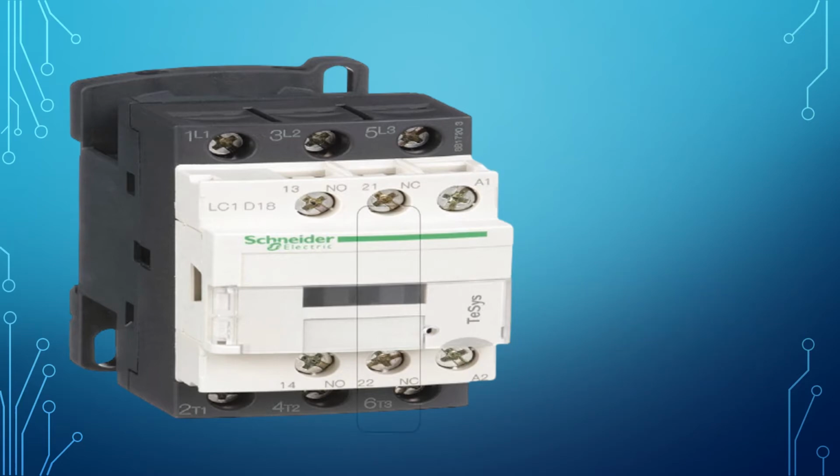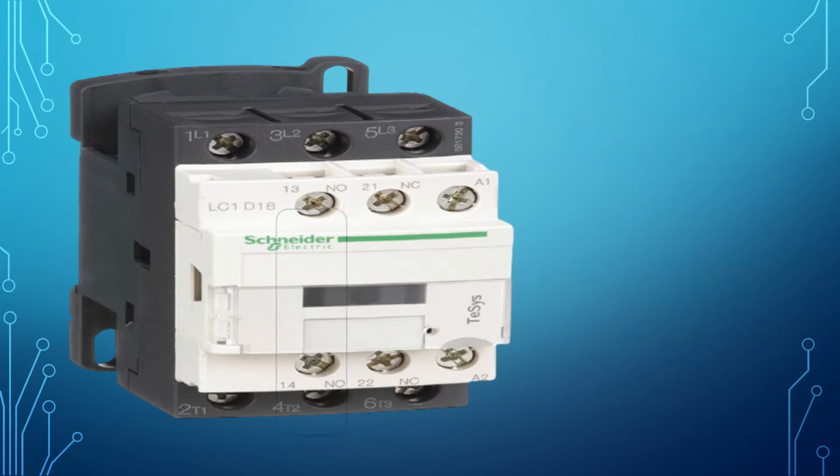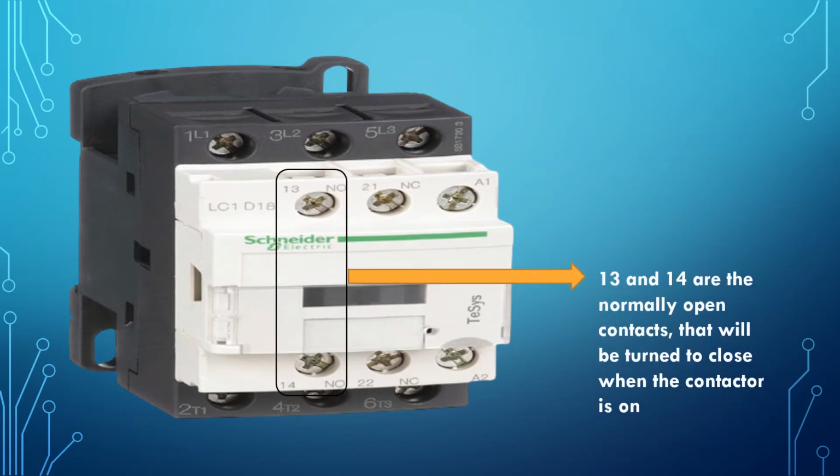21 and 22 are the normally closed contacts, that will be turned to open when the contactor is on. 13 and 14 are the normally open contacts, that will be turned to close when the contactor is on.